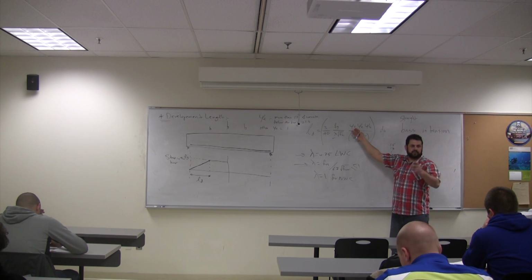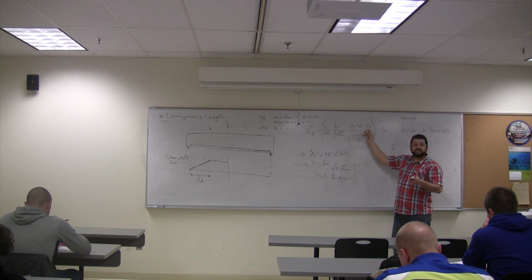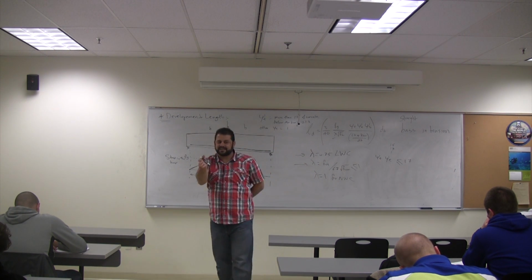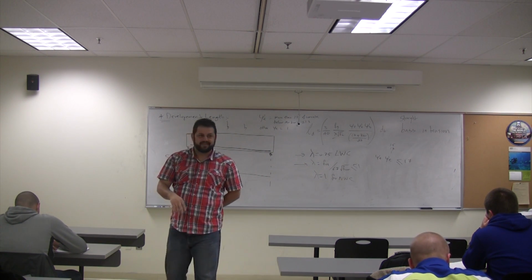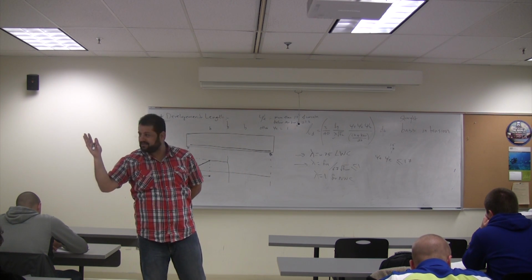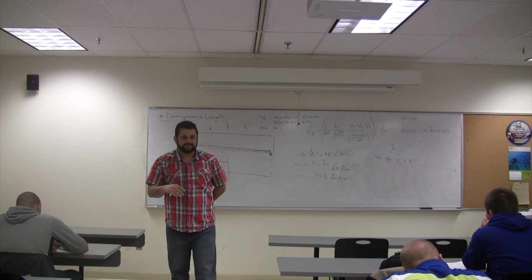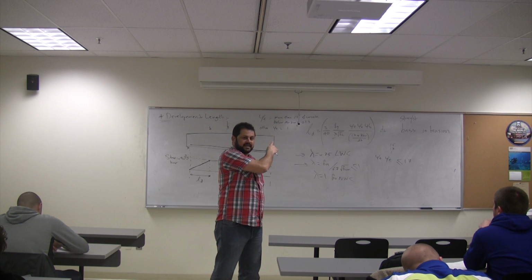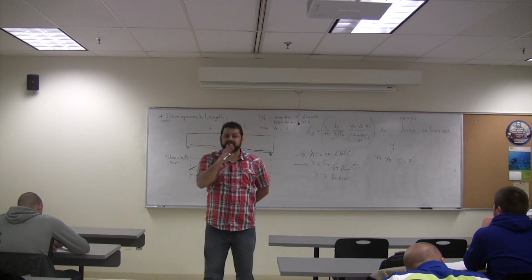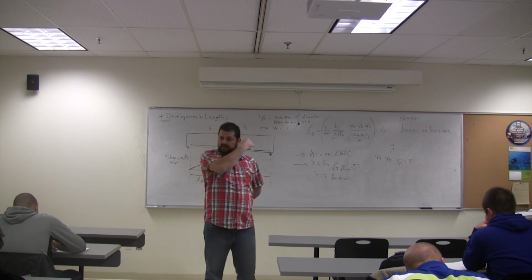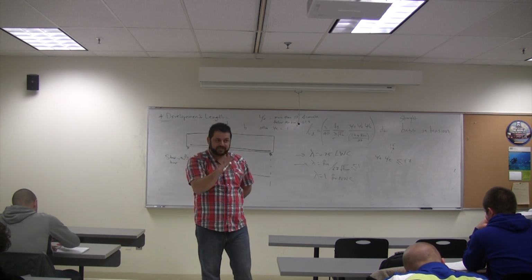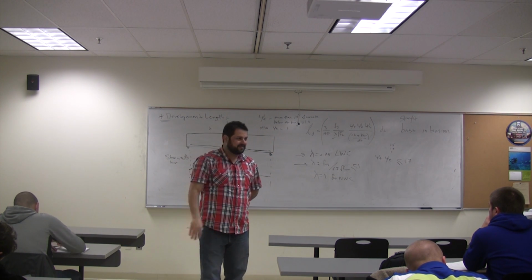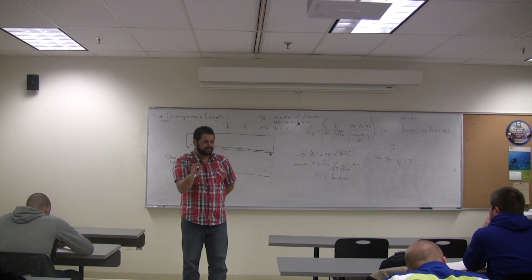So psi T location, top or bottom, psi E, epoxy or non-epoxy, psi S, size factor. So easy, look at this. Number 6 and below, 0.8. Number 7 and up size bars, 1. Number 6 and below, take psi S equal 0.8. Number 7 and up, 1. But this is the code requirement. The code people say, we encourage you to take it 1 all the time, for all bar diameters. They say it's recommended to take it 1.